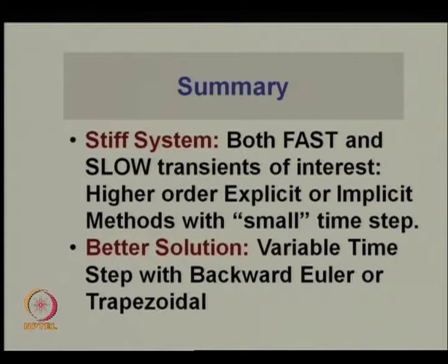Now, of course, the important thing implicit in all what I am trying to say is that we are trying to complete our numerical integration as fast as we can. Somebody may ask, well, you have seen this simple RLC circuit, to numerically integrate this for say 30 seconds even with a time step of say 100 microseconds or 50 microseconds should not be a problem on today's computers.